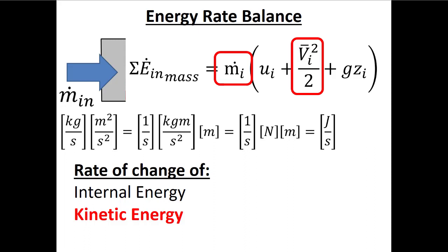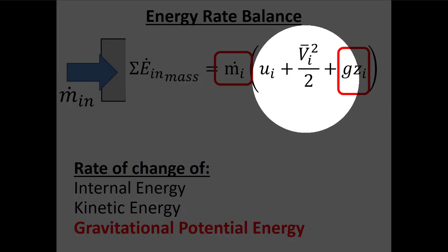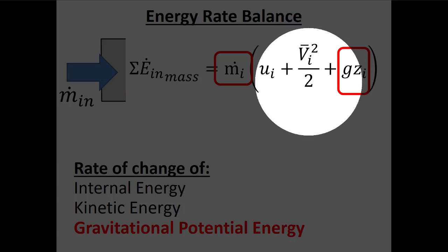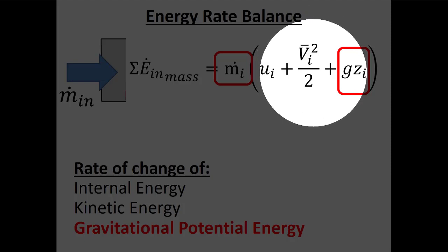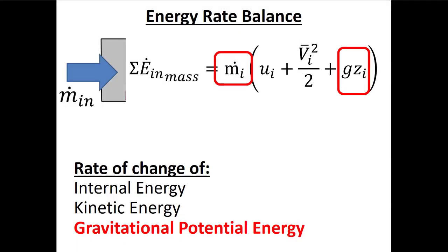So this is not going to work out exactly the same every time, but if the kinetic energy term survives, right, if we're interested in kinetic energy, we have to be worried about the units. So if we want to turn this into kilojoules per second so that I can add apples to apples when I'm going inside my bracket here, now I would multiply by 1 kilojoule divided by 1,000 joules because I want to get rid of the joules on top, and there's 1,000 joules in a kilojoule. So I'm going to leave this as v squared divided by 2, but if I was doing this problem, I'd have to look and see, okay, what is my velocity measured in? And if it's in meters per second, and this is a metric problem, then eventually I'm going to divide by 2,000 here. But it's going to be different if it's kilometers per hour. So I don't want to put the unit conversion in here automatically. I want to leave it like this and then think about it when I'm actually doing the equation.